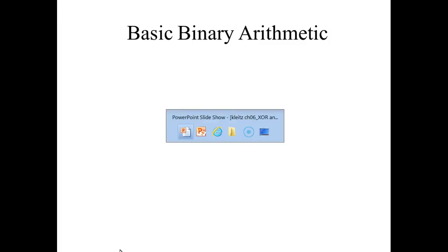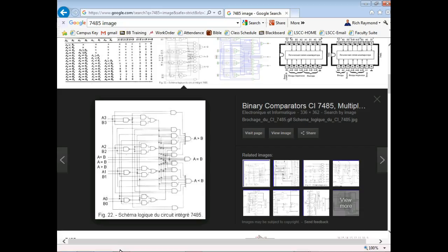But you've got to understand, these guys don't handle a bunch of power. And if they don't handle a bunch of power, we can get a lot of integrated circuits on a single wafer. But there's the exclusive OR, and then all these gates are in here to take inputs from another stage if we want to cascade them, and it gives us the outputs over here. But all it is is just ANDs, ORs, NANDs, and NORs, right? That's all it is.